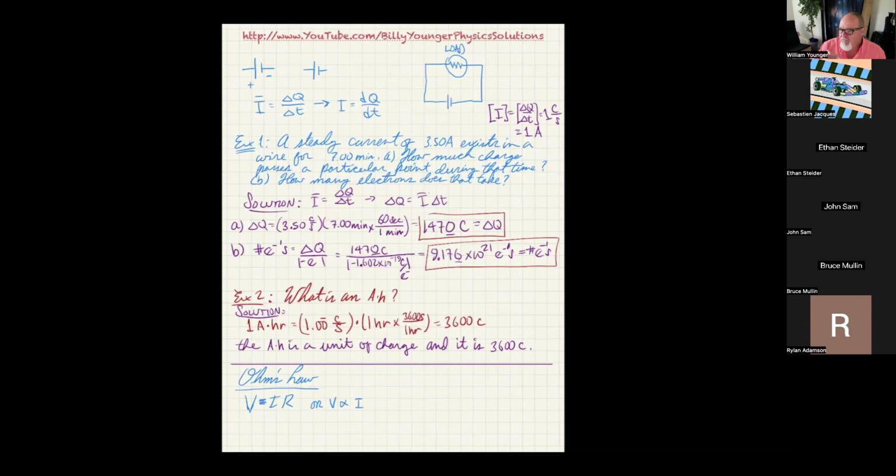Now, in that context, if something obeys Ohm's law, and what I mean by that is that thing obeys Ohm's law at least within a certain range of values of voltage and current, i.e. certain powers, and every time you apply a voltage and a current, you get the same value R each time, that device would be called an ohmic device. So those little resistors that you use in labs, they're ohmic devices.